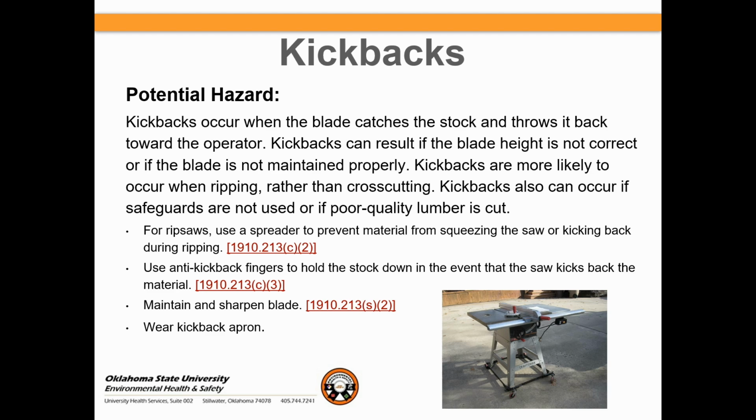I don't know how many of y'all have ever heard of what they call the kickback. Kickback is very common to see, particularly in the industry where they do a lot of cuts with wood. Kickbacks basically result from the blade height not being correct or the blade not being maintained properly.